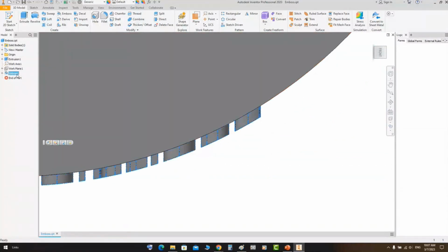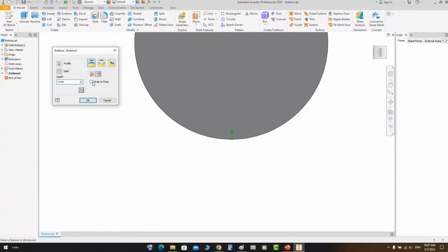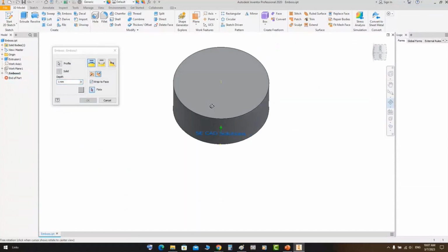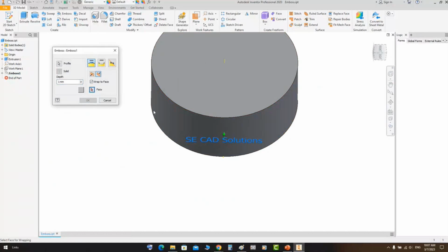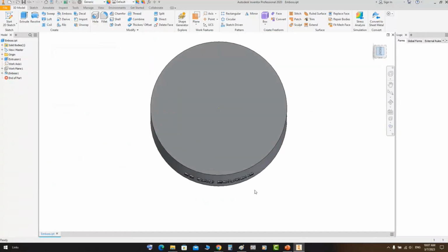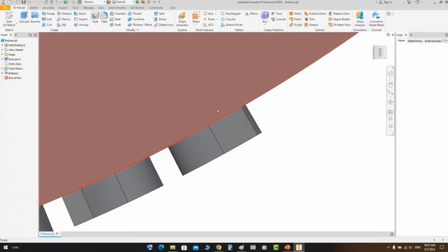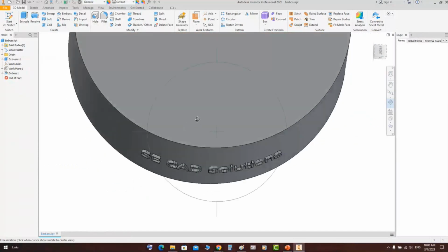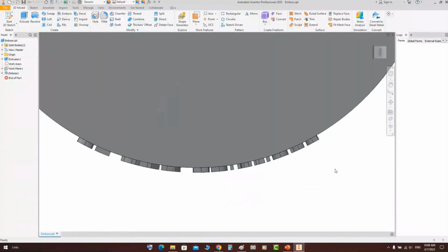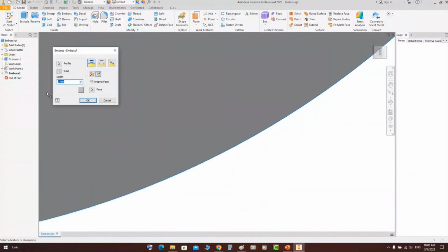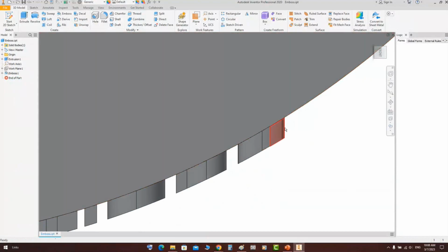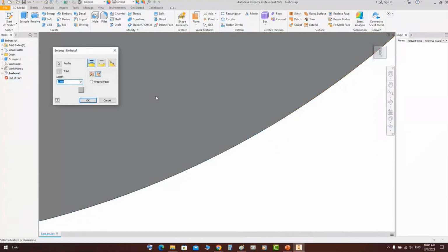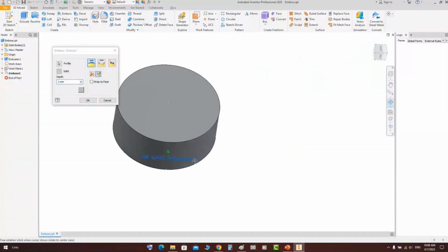If you would like to make it wrap to the face, you will need to select that option, wrap to face, and from face select that face. If you click OK, now if you take a look from the top view, the lines will be perpendicular to that surface, which is the cylindrical surface, not to the origin plane. So let's make it back. By double clicking on this, let's remove that one. So you can catch the difference between that one and the other.